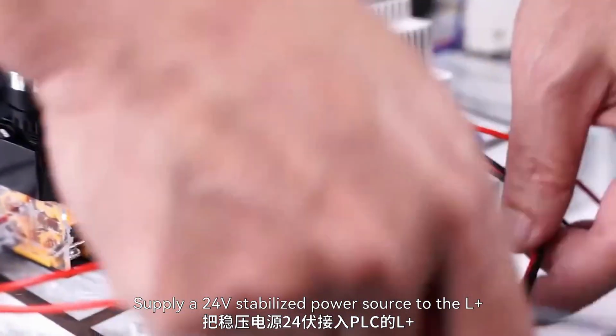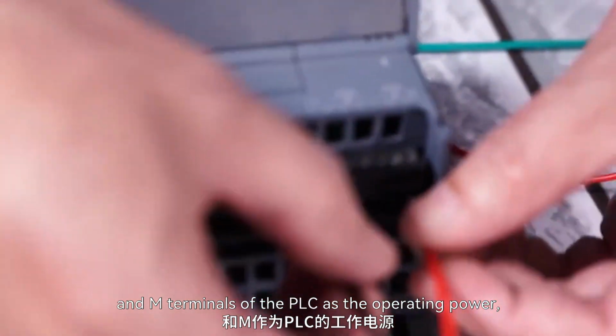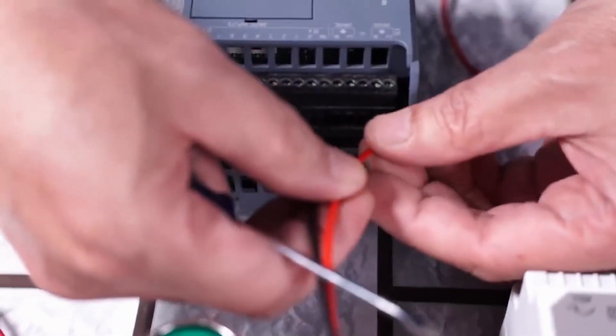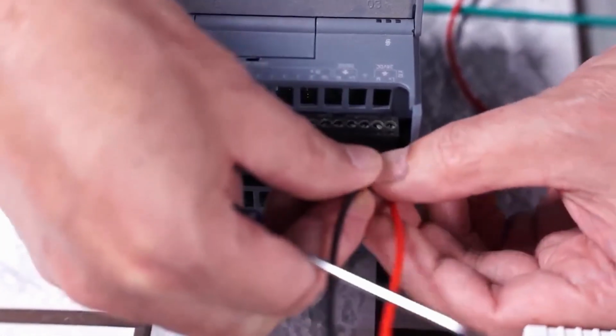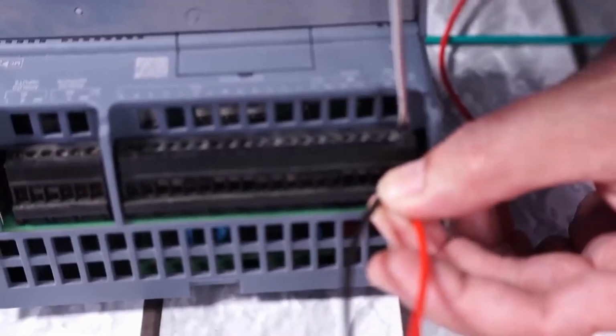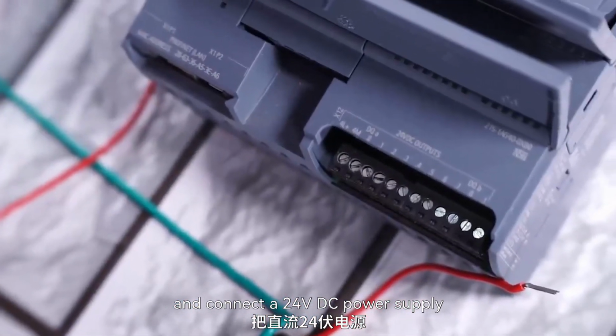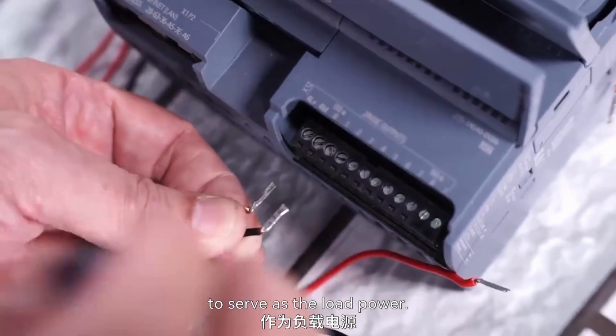Supply a 24-volt stabilized power source to the L+ and M terminals of the PLC as the operating power. And connect a 24 volts DC power supply to the 4L+ and 4M terminals to serve as the load power.